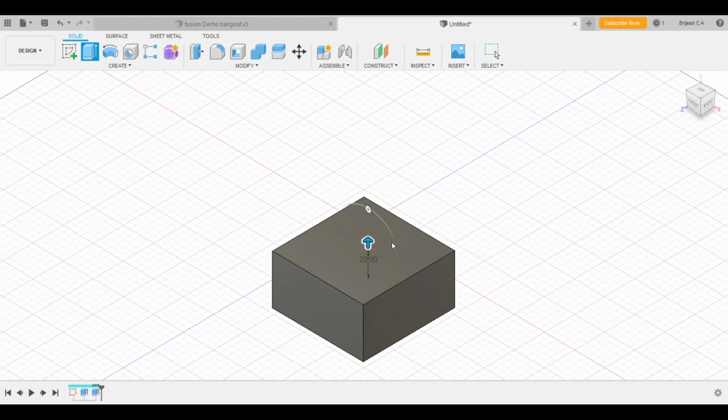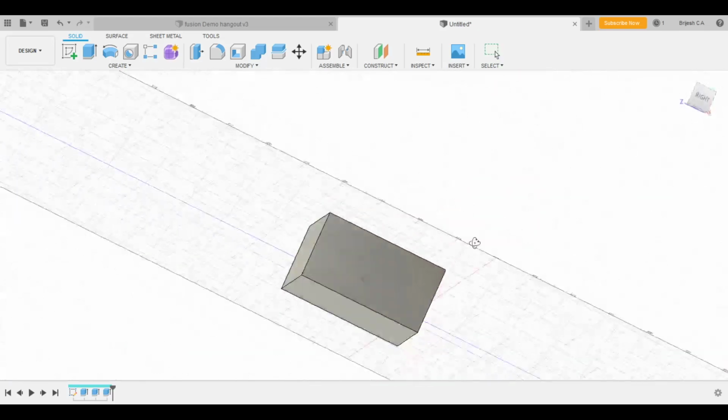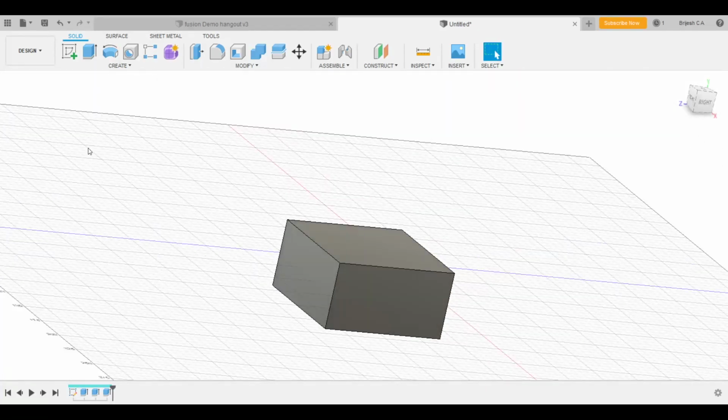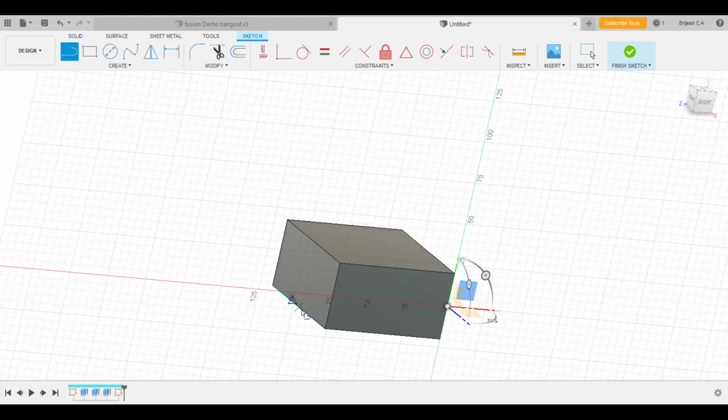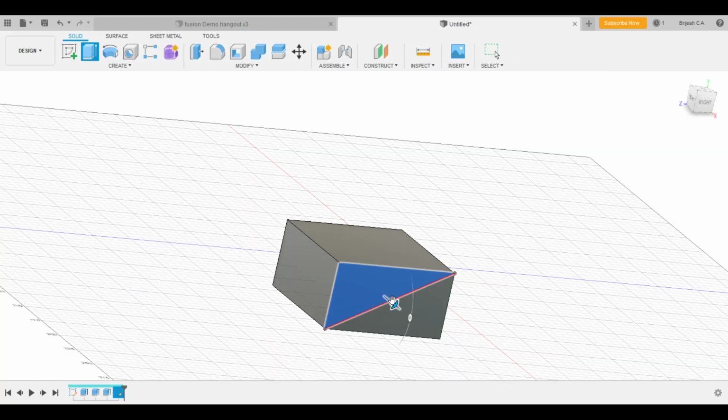Okay. So sir, if you want to create a slope, how will you create a slope, like a right angle slope? So you're saying cannot move it left or right, right? So how can you create a slope when you want to create? So what I do is I'll create a line on this surface. I want to create a line from here to here, and then this one I'm going to extrude it off.